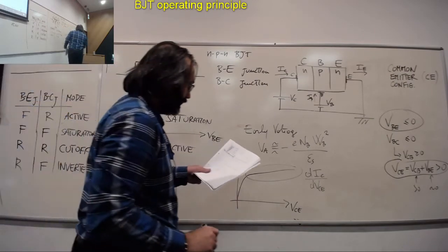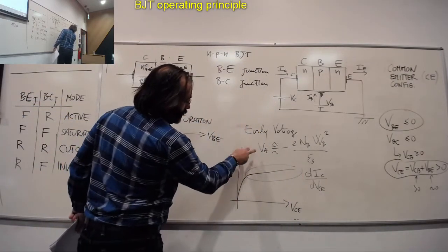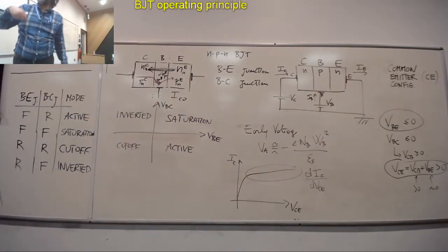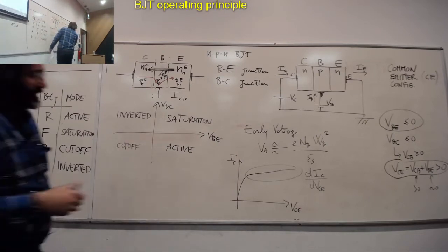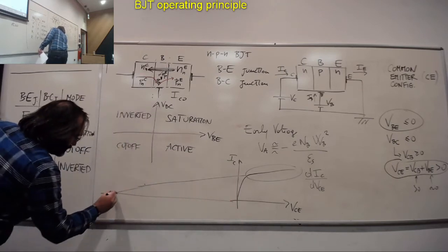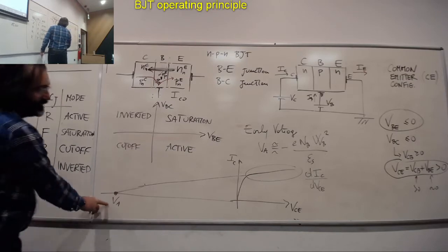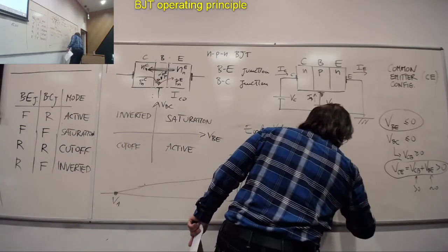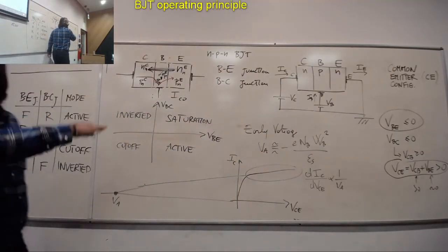And what we've realized from this image I've put there is that this slope will meet somewhere here, VA. All of them, all the possible characteristics meet there. So the slope really is proportional to 1 over VA, isn't it? The farther VA is, the flatter this becomes.